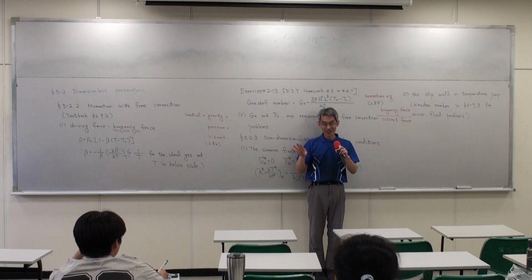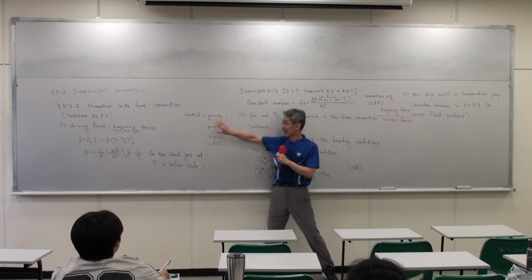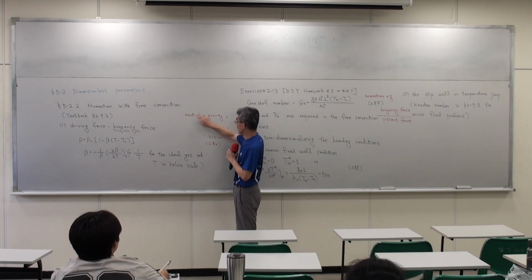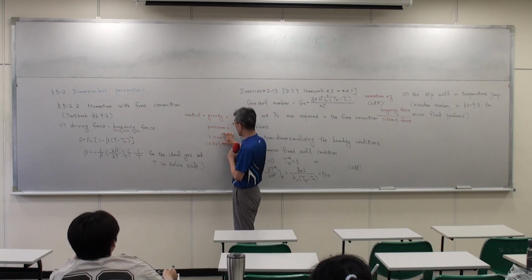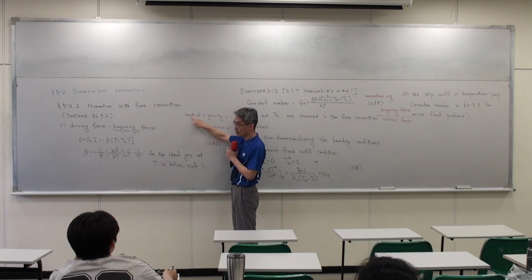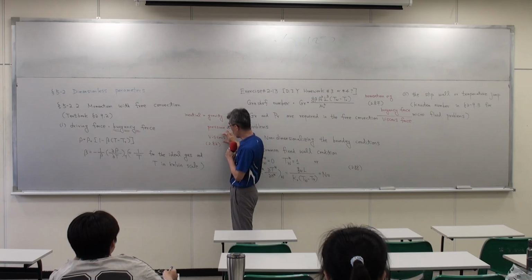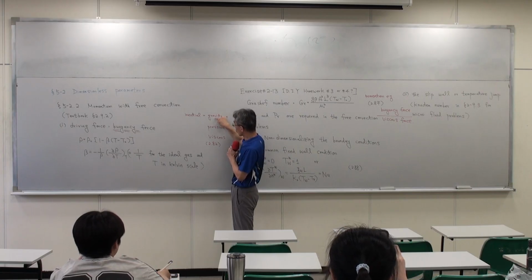So your dimensionless equation is not only this divided by the right-hand side. You can divide every term, so this will become the Reynolds number, this will become 1, this will become the pressure compared with the viscosity force, and this will be gravity compared with the viscosity force.